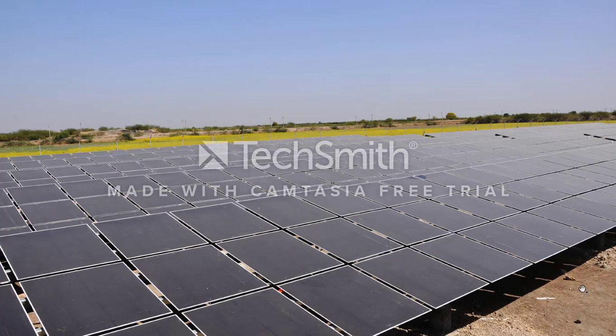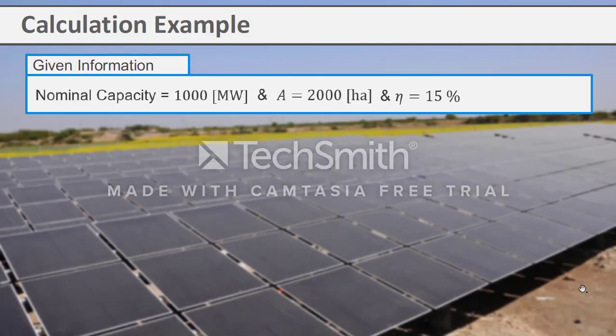In the following example, we want to calculate the energy yield and capacity factor of the Gujarat Solar Park on the top of the west coast in India. The Gujarat Solar Park in India is one of the largest combined solar farms in the world. It consists of 84 large-scale projects that have a combined nominal capacity of 1000 megawatt. The surface area of the farm is 2000 hectares and we will assume a moderate estimation of 15% for the total PV system efficiency. First, we want to determine the annual average energy density.